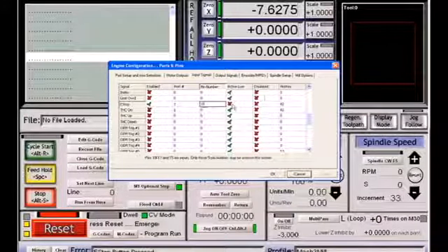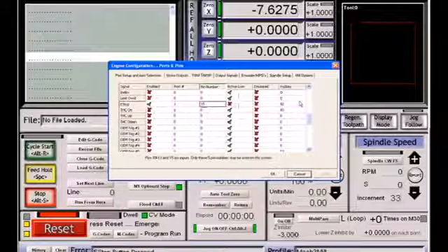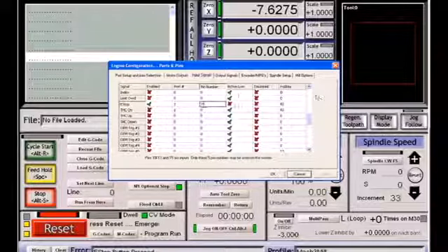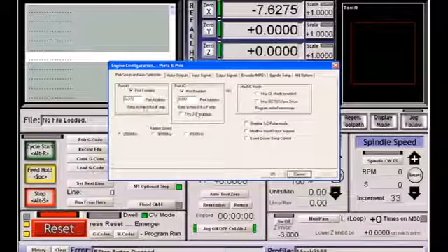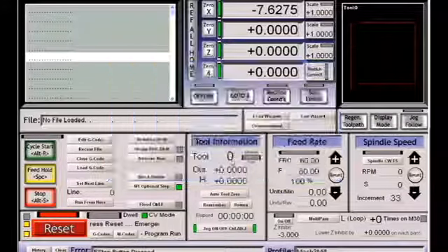You can see that the active low is checked off, therefore a high signal is what is going to trigger an e-stop. At this point, you can pretty much stop using this configuration. Your primary task here in this setup is to get your motors running. So all you need is an e-stop signal, the proper motors turned on with the proper pins, and your port set up correctly. Beyond that, you don't need anything to get your motors to run, so let's hit OK and